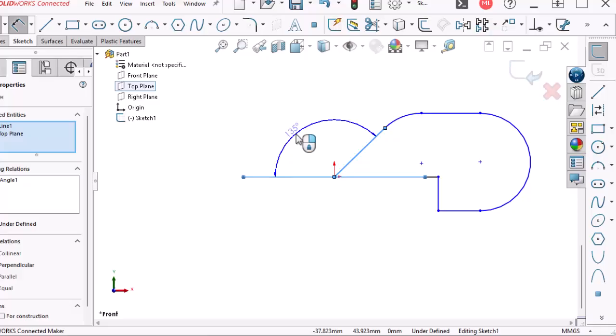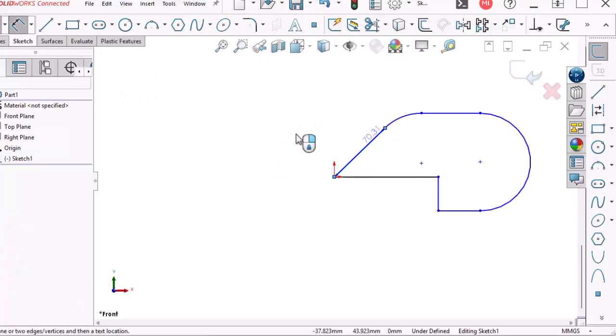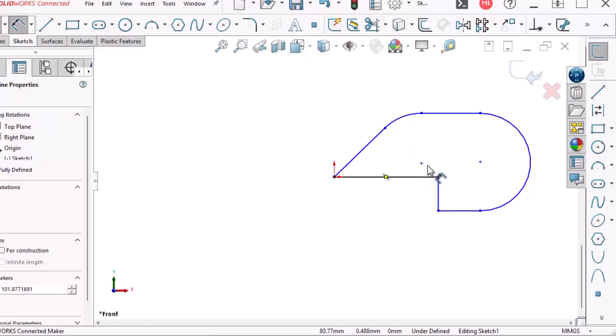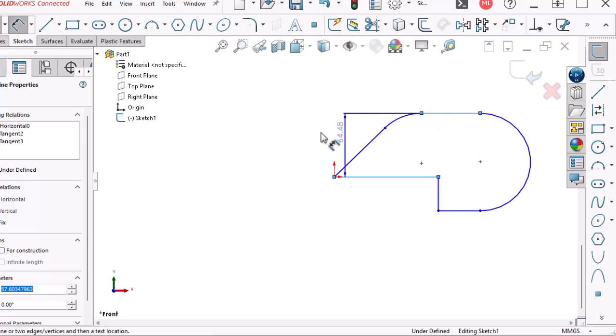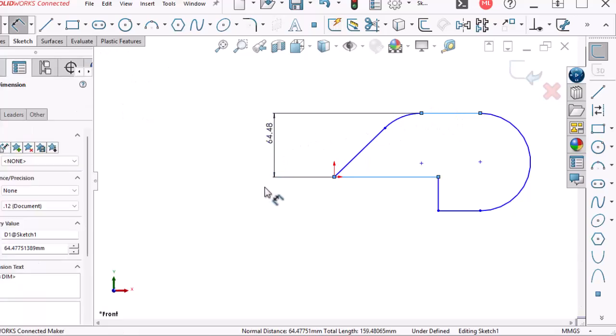and you can get the inside or outside of that very easily. Also, one of the cool things about the SolidWorks dimension tool is that if you've picked a number of things, for example, I just picked this plane and I picked a line earlier, you can hit escape and it will dump whatever the last thing was that you selected. So the last thing I selected was the plane, and now I'm back to just having the line selected. If I press escape again, now I'm still in the tool, but I don't have anything selected, so I could pick something else, like this line down here and this line up here, and put that dimension in.